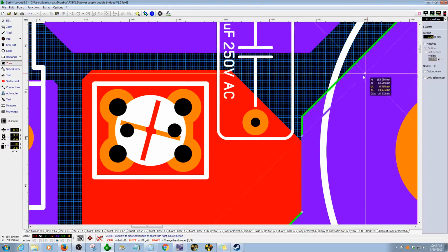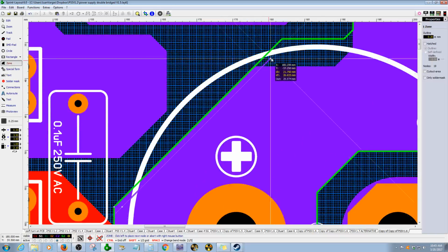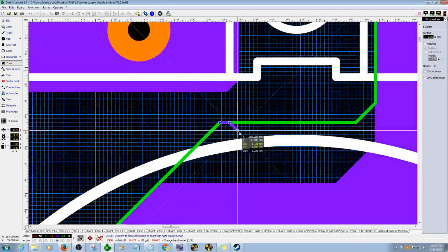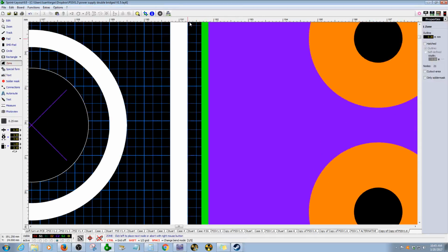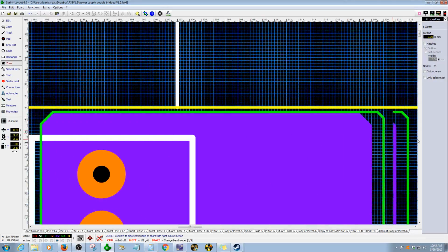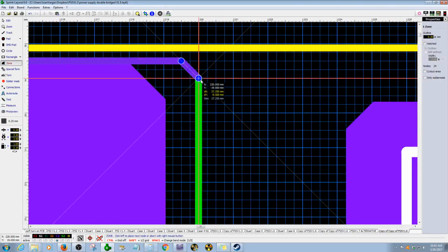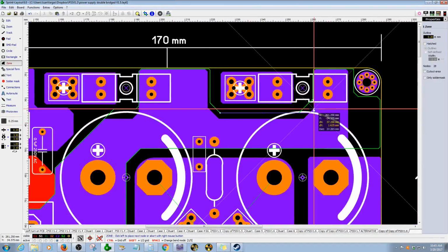But the PCB also is another thing. The PCB is 1.6 millimeters in thickness. So I'm not sure if the best choice is to have a thicker one, a 2.0 millimeter thickness, or the copper clad PCB. Just the fiberglass area. I'm talking about the thickness of the fiberglass area, not the copper area.